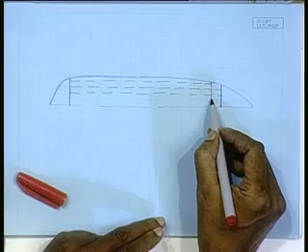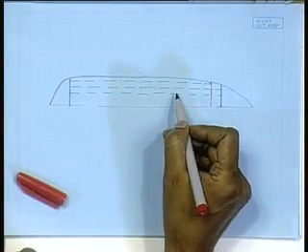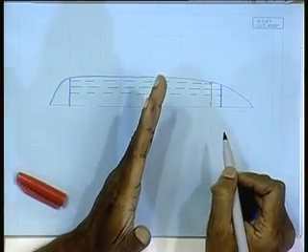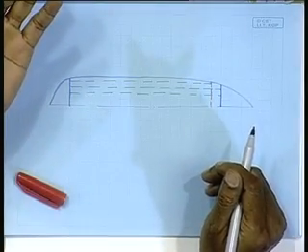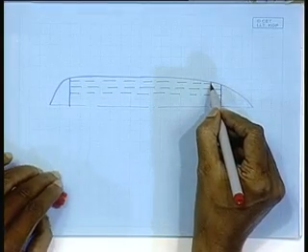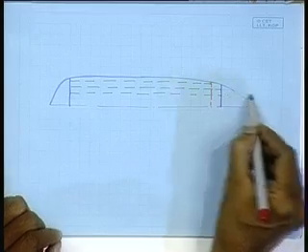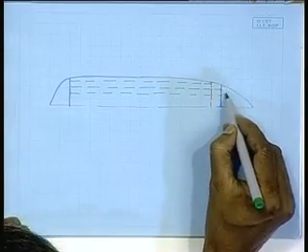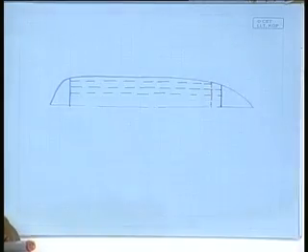So, this deck transverse will be widely spaced. For a longitudinal framing system, the transverse member will be spaced 3 to 4 times the frame spacing. Anyway, so it is terminated here. The other two are terminated in the fore peak bulkhead. Then what happens if I go still forward? If I go still forward, then it becomes very difficult, because the shape is closing sharply, right?